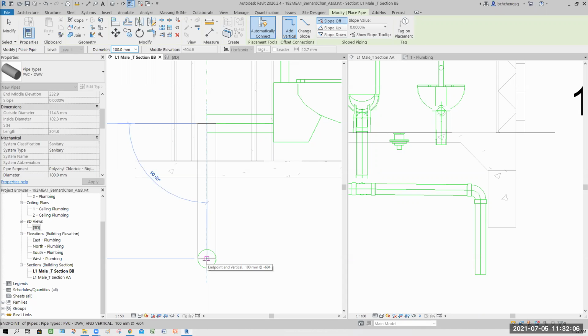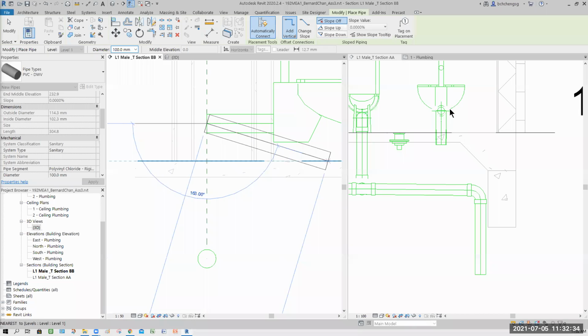Second, in order to snap them nicely, you don't say snap to endpoint because this piping is sloping. Sloping in the sense that here there's two endpoints. One is at the rear, one is at your section. So if you select the wrong one, your piping might join differently. So normally I'm very careful. Once I drop to here, I will swap to my view here to ensure minimum error.